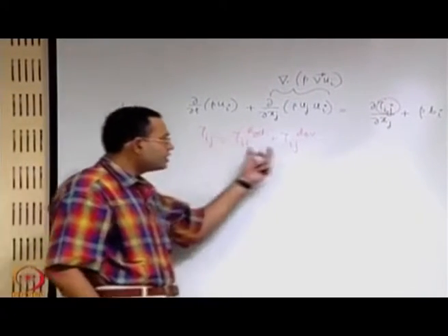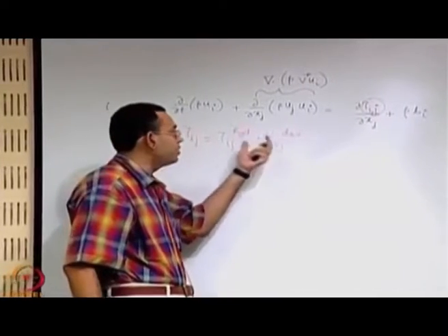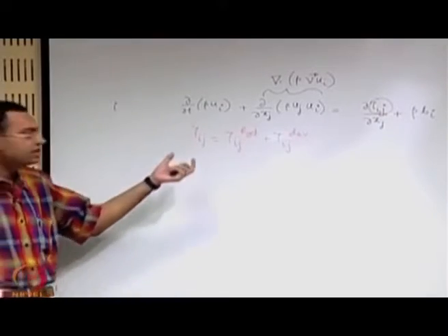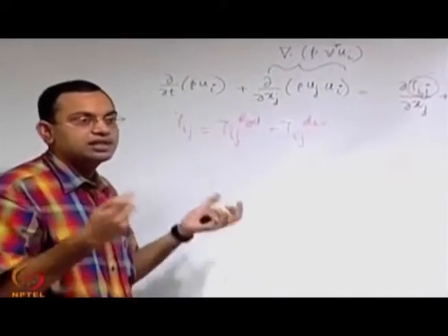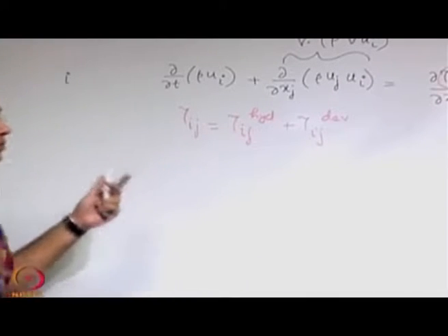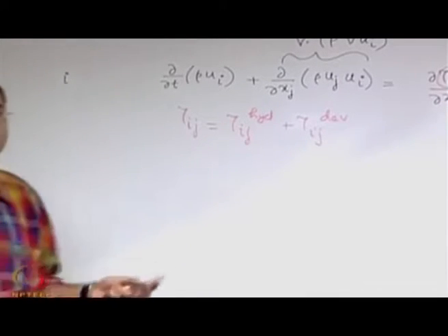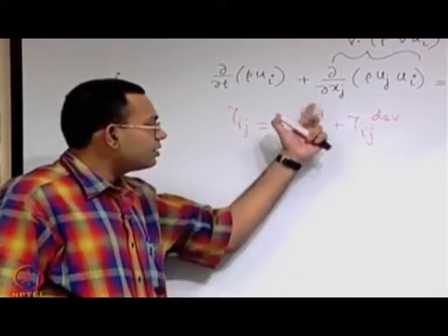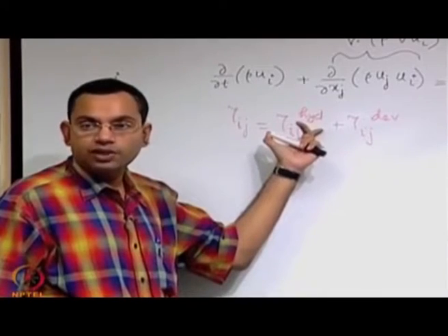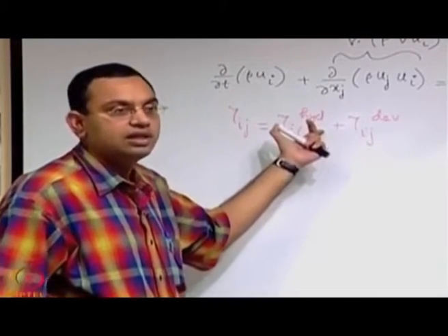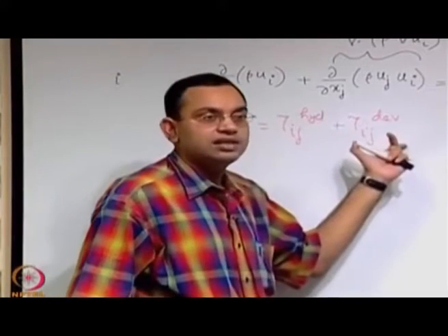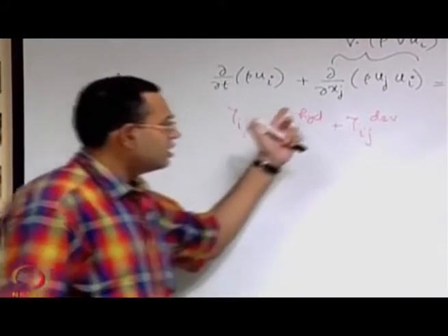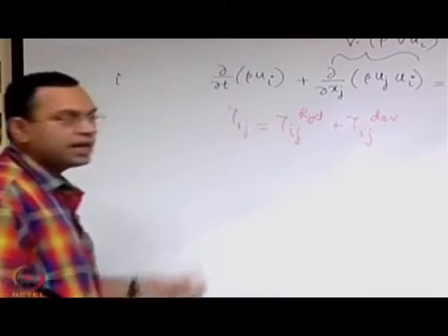Whatever is not a function of deformation should also be prevalent when the fluid is at rest, because then its state of stress is denoted by a simple normal stress condition, which is because of the pressure distribution, and that manifests in this hydrostatic component. It does not mean that when the fluid is in motion it is not there, it is definitely there, but something additional is attributed to the deformation of the fluid, and we figured out how we relate that with the rate of deformation.